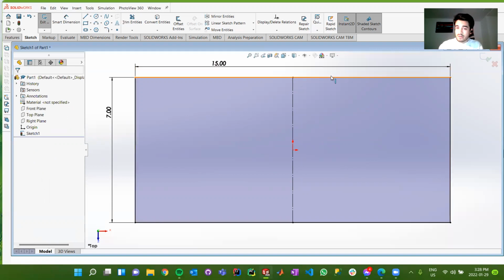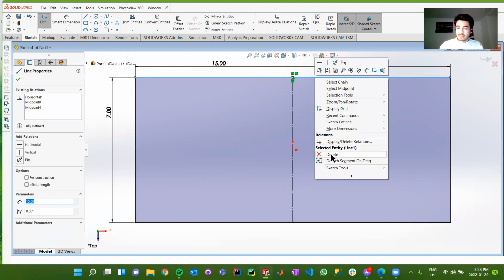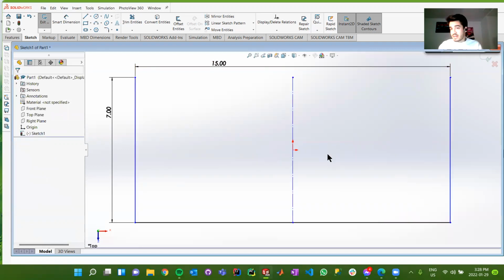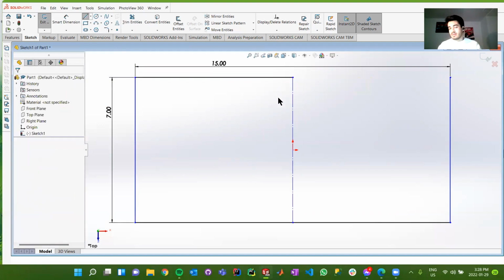So if I right click on this top length here, so let's do that and click delete, you'll notice that the whole line is gone. And, sure, we want to get rid of the line on this end of this line, but we want to keep it on the left-hand side, right? So essentially, if we do that, we're going to have to restart our CAD and click line and make another line like here. It's possible, it's just not ideal.